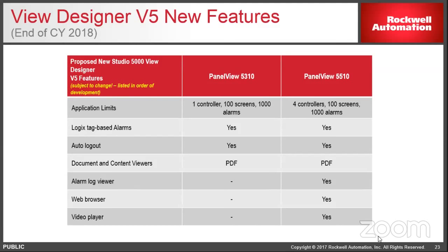And then one quick note, from a 1 controller to a 4 controller, obviously we are talking about this with Rockwell controllers only, so it does not have third-party protocol support. But you have to remember that if we bring in those protocols into a Rockwell controller, whether it's a Molex or ProSoft gateway, it's now a Rockwell protocol to the unit. So when we look at the architecture, that would be how we would end up looking at that. Where traditionally in a PanelView 7 world, we're able to go natively using Kepware that's built in. In this product, we would bring those data points in via the controller and use either a DIN rail mount or in-chassis module to be able to convert that.